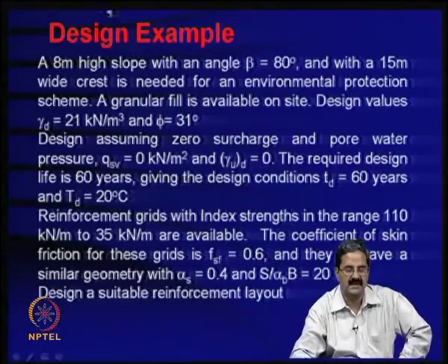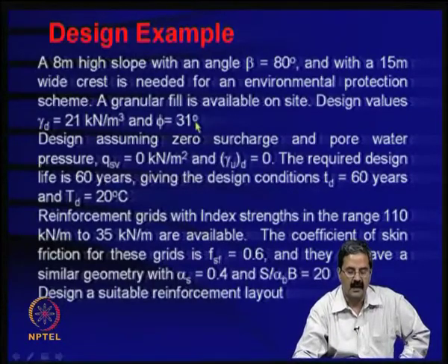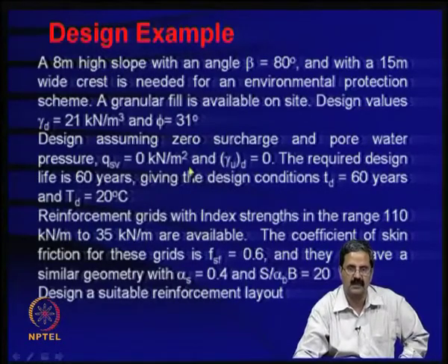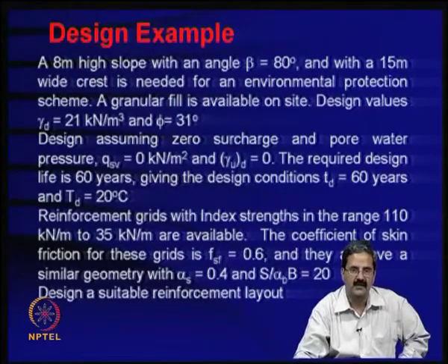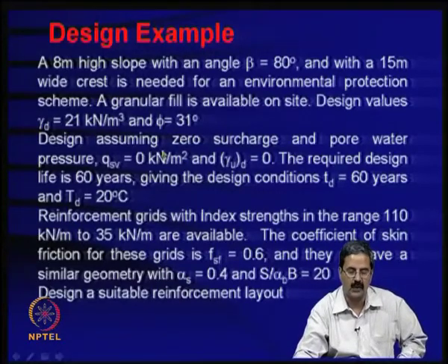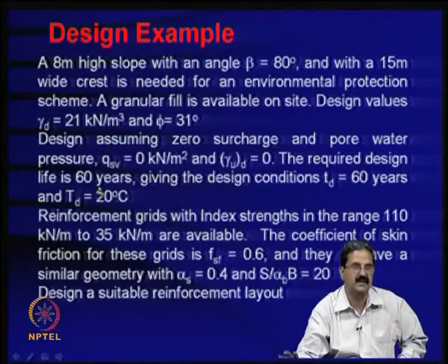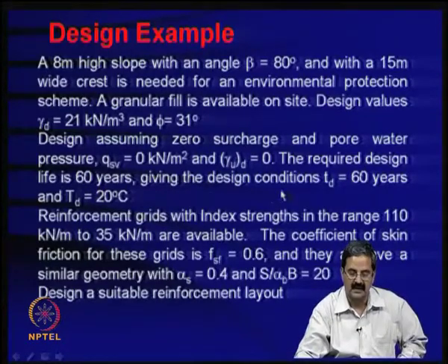That surcharge effect is considered, okay. So, in this design example I am only illustrating, but suppose you have a problem with surcharge, particularly when you are trying to design using IRC and other guidelines, you need to know how to handle surcharge. The required design life is 60 years, okay. Then the design conditions are TD equal to 60 years and the design temperature is 20 degrees, okay.